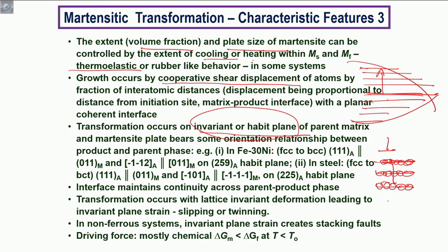In case of Martensite, we actually require planes which are slightly wide apart, but the atoms very close by. So, just the opposite. For Martensitic transformation, we require wide apart but closely packed planes, and this kind of restriction brings us to the possibility of seeing this transformation occurring on some specific types of planes called habit planes, which is described here.